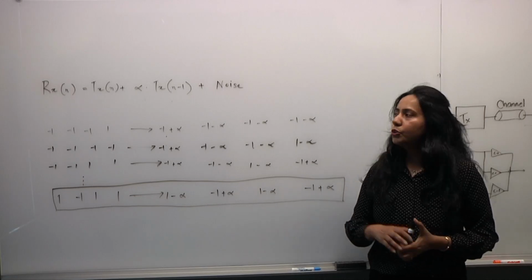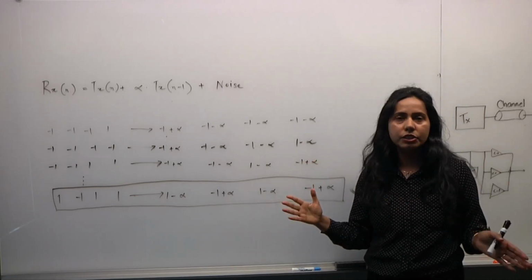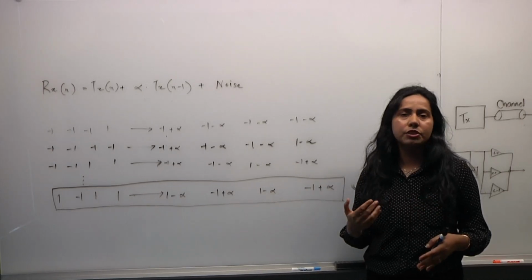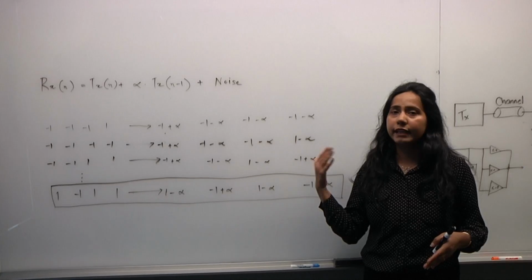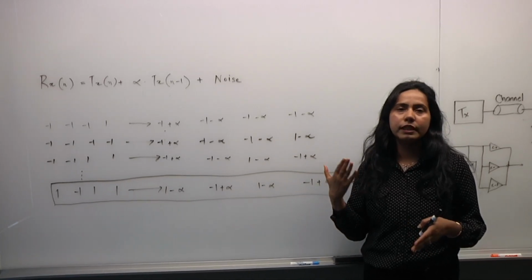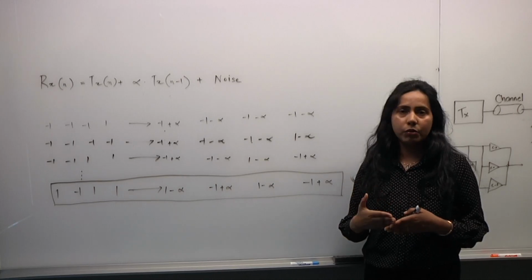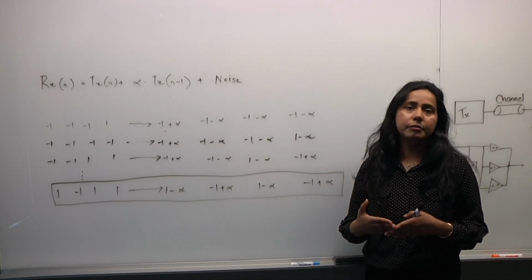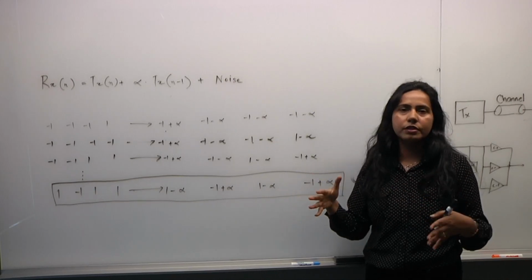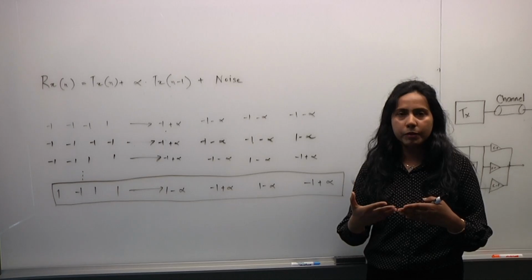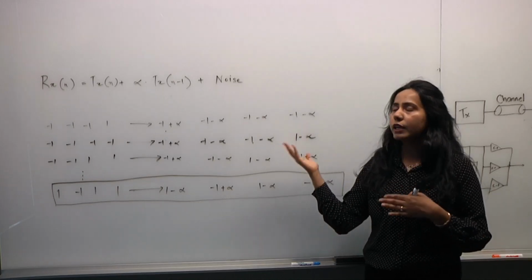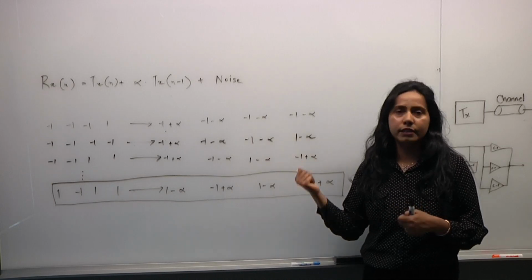Right, right. So when you have a larger channel, a lot of noise, and discontinuities in the channel, then you would use these advanced DSP techniques. With MLSD, you have to remember that you need more area, more power, and it will add a little bit more latency. So if you have a different kind of channel in your system, you might want to remove some of the taps from your conventional FFE, and you can also shut down the MLSD when it's not required.